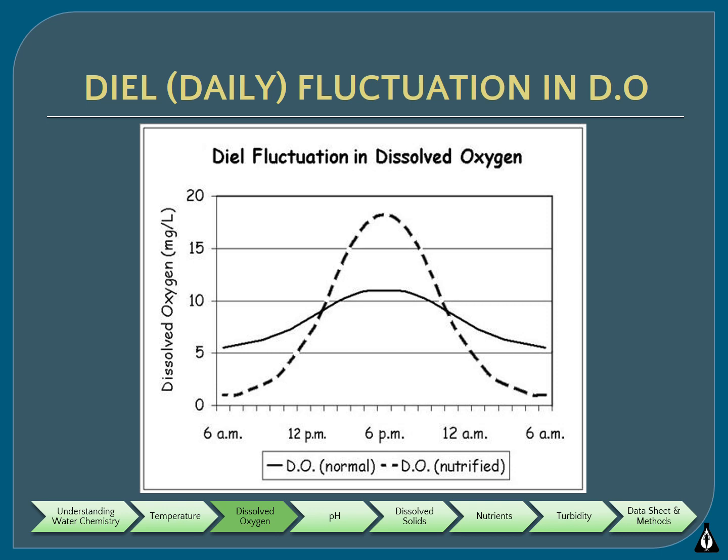This is why water quality professionals try to take dissolved oxygen readings early in the morning so that they can potentially see this increased swing in dissolved oxygen throughout the day.